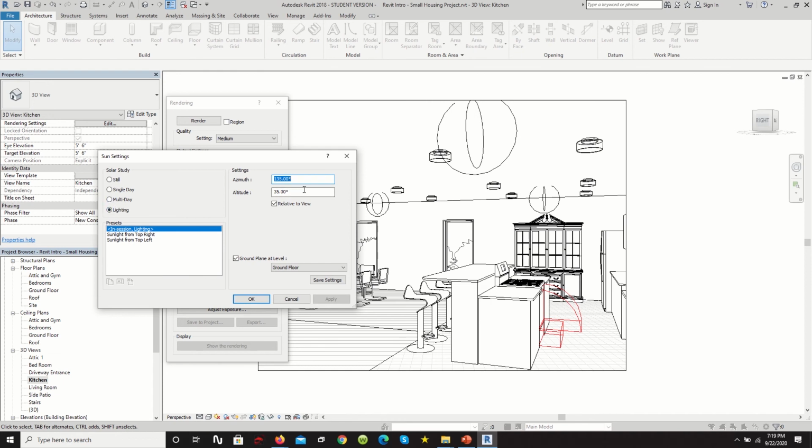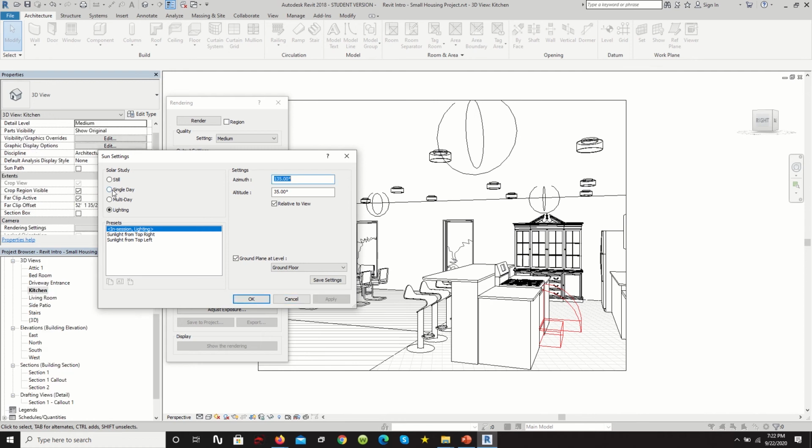And going here, we can pick the lighting, like the time of day, all that stuff. You can pick a certain location. If you need the specific lighting qualities of a certain location, you can do a single day at a single time, and choose what time and all that stuff. What I'm thinking of doing is having the sun up at a specific angle. Actually, I'm probably going to do a specific time of day, because that's going to be a little bit more relevant. So let's do something like the morning hours, 11 a.m. Actually, we can even have an evening sun. Let's do that.